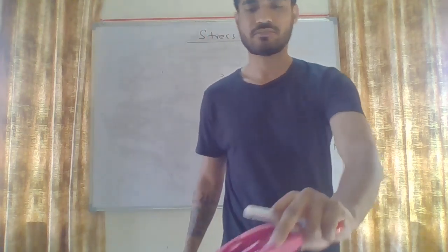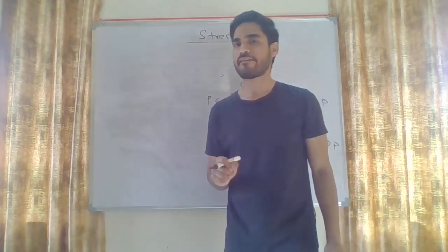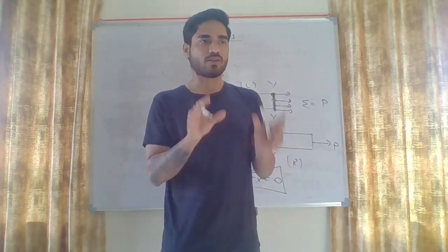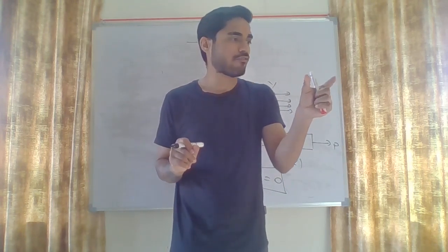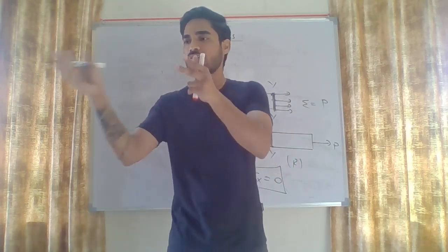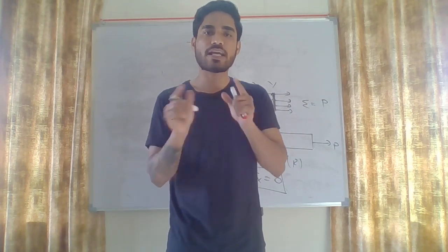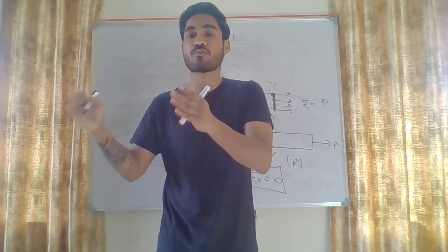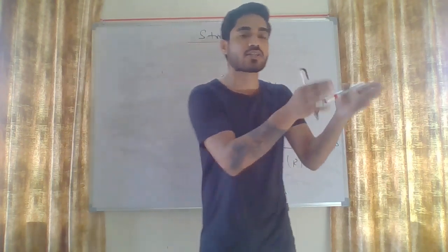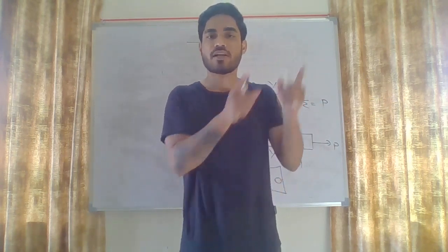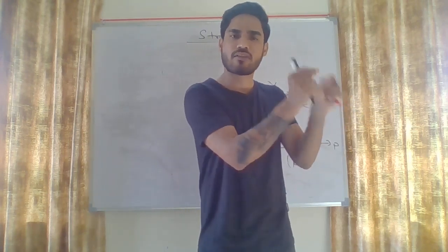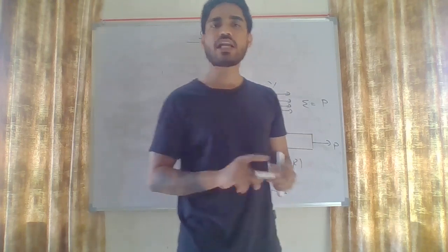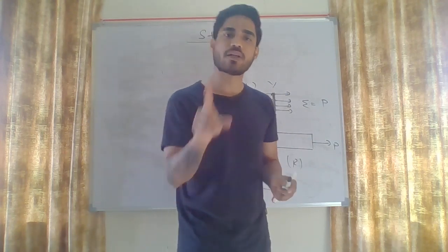So the first thing, why are internal forces developed? Internal forces are developed to resist the deformation. Let's say there are two springs. One is deformed by 1 mm and one is deformed by 5 mm. Which one will experience more internal force? The spring which is deformed by 5 mm. This is trying to resist 5 mm deformation, and this is only trying to resist 1 mm deformation. So in 1 mm deformation, internal force will be less, and in 5 mm deformation, internal force will be more. So internal forces depend upon the deformation.